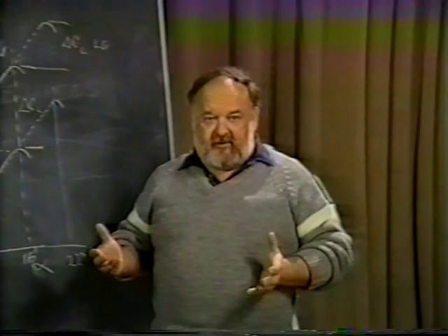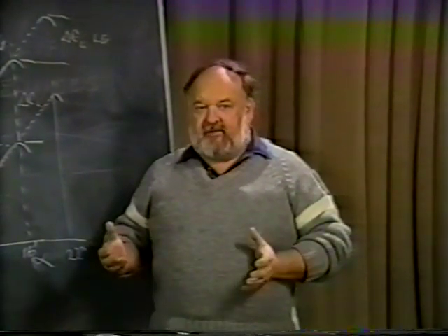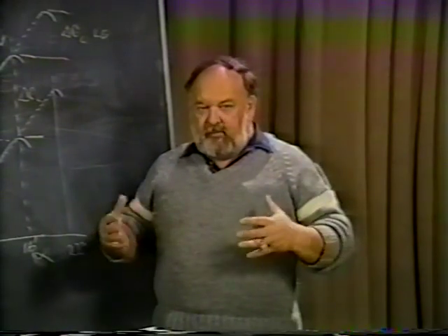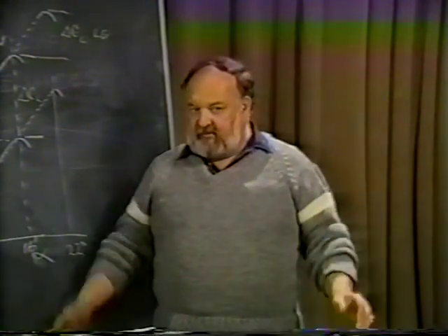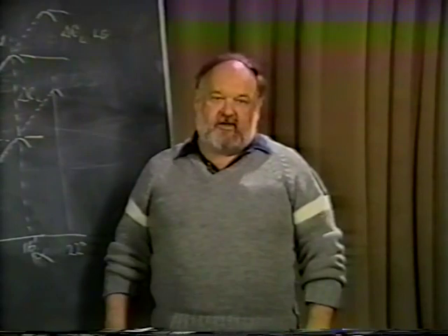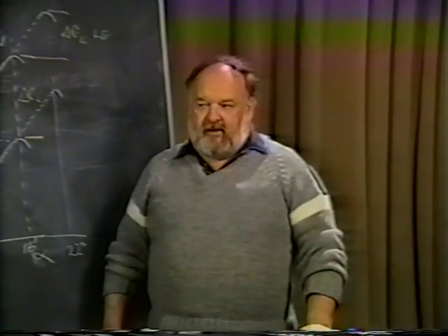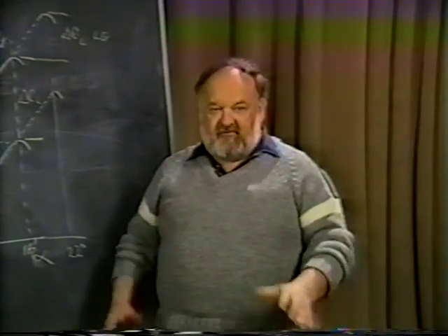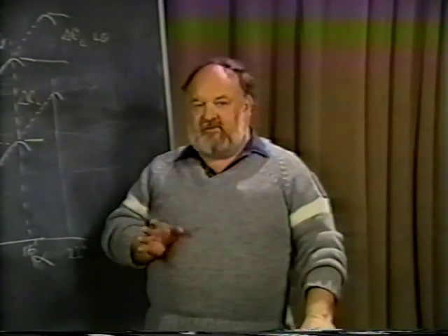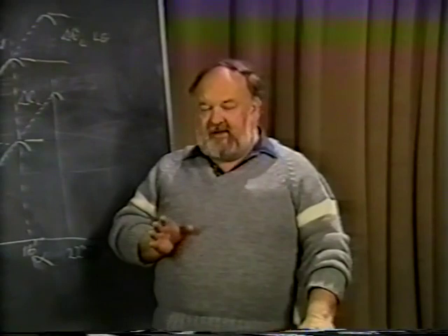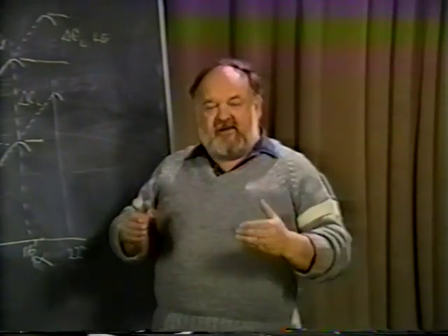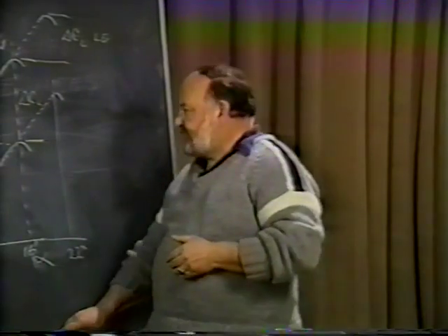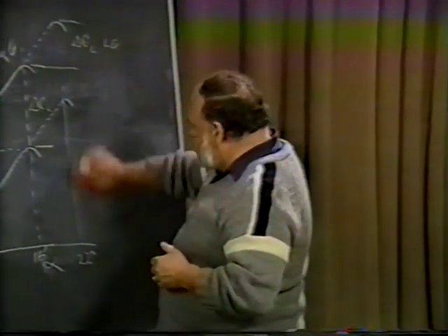An all-flying wing, for example, however, has a difficult time in using the flap, because by putting the flap on the trailing edge, you generally will produce a pitching moment that is greater than what the flying wing's stability characteristics can tolerate. Northrop, when they built the B-35 and the B-49 flying wings, needed to use some form of flaps on there. And what they did, they used a split flap. But even in that case, they could not use the split flap all the way back at the trailing edge. And what they really did do is this.